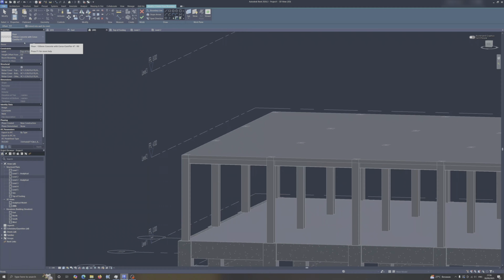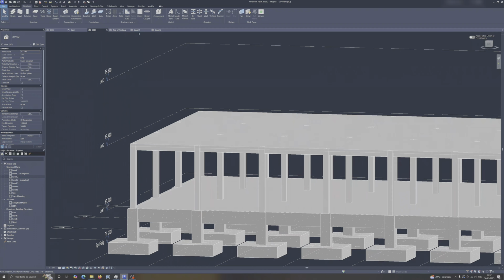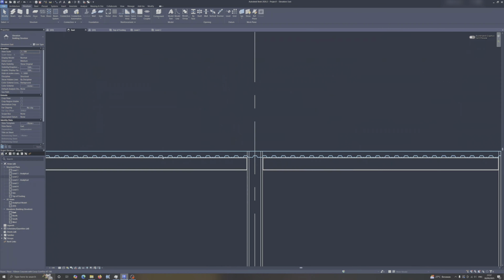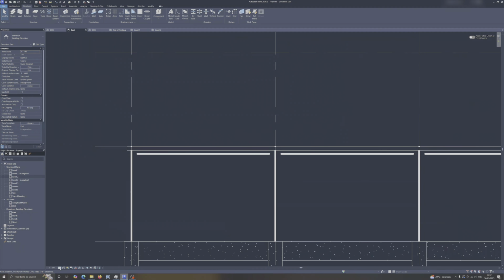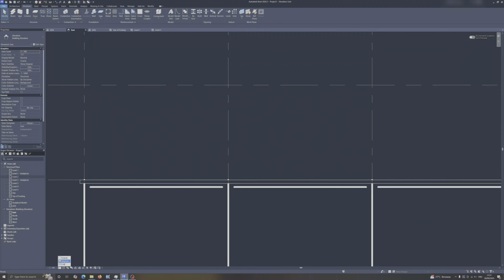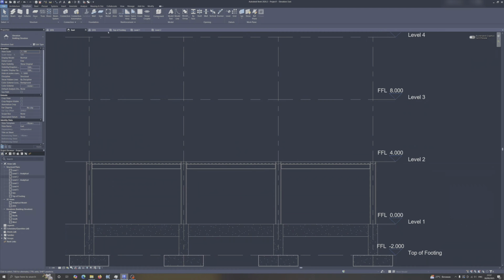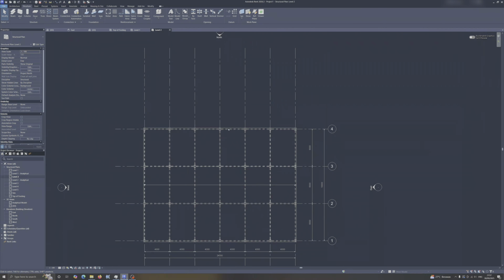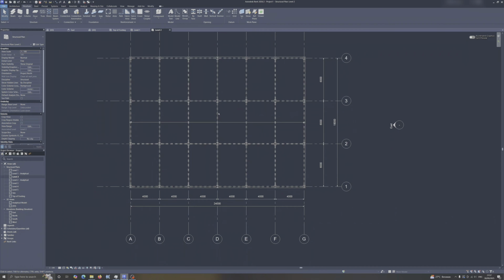And in the 3D view, you can't see the profile of the composite floor over here, or the bond deck. You can only see that in the elevation view over here. But if you were to use a coarse level of detail, you won't be able to see it. You can only see it in the medium to fine range over here. So that's one thing to note.